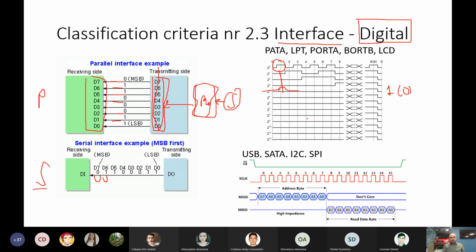Now, it depends of course on the length and the parameters of the wires. For short wires, it's good to have parallel, but for longer ones, better to have serial. Why? We can, of course, protect the wire by inserting it inside a shield. So it will be protected, but this means we have some material to spend, and material costs money, and high quality material even more money.